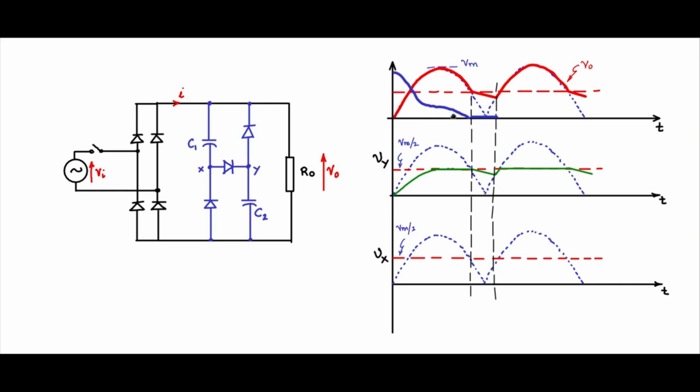This first cycle charge, it is like this. The second cycle onwards you will see that it will just be in this fashion. Now you see that the conduction period of this current has been widened so much, and therefore the peak would be significantly lower compared to the normal capacitor rectifier filter capacitor circuit.